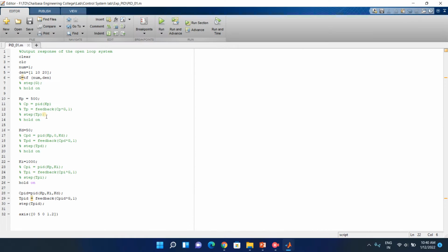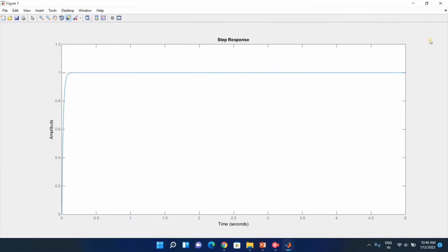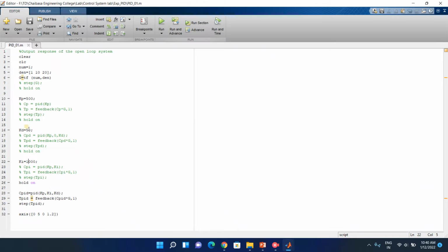because of the integral controller, and the PI controller. See, the value of KP is 500, but KD has damped it. KP is very high, but KD has damped it, but KI has to be high also, otherwise it will not be able to make the error 0. So this has to be kept in mind, that KD cannot be too much, but KI has to be high. Often in many cases KI may be greater than KP also. This just depends upon the tuning.